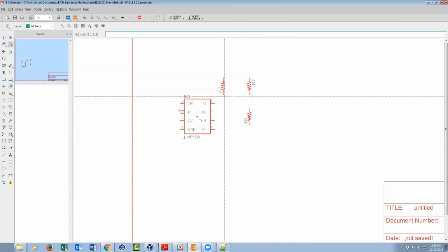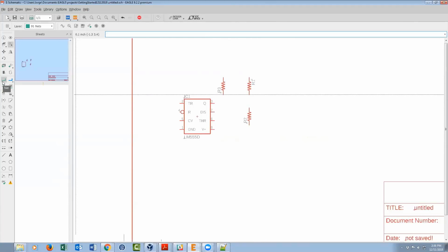So to connect components in Eagle, what you want to use is the net command, okay? Do not use wire. I'm sorry, line. Line is for drawing. Neither wire. Just use net for net connections, period. Net.